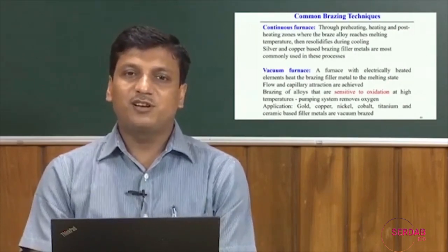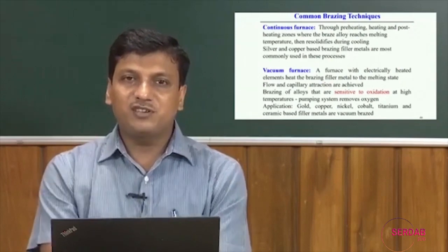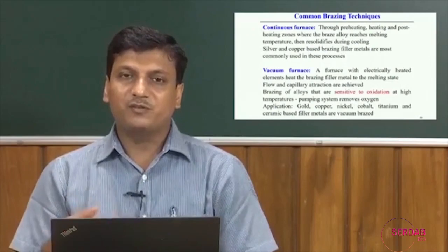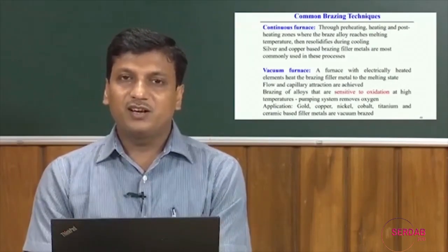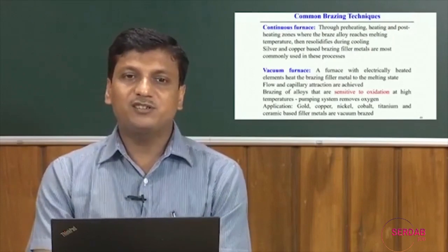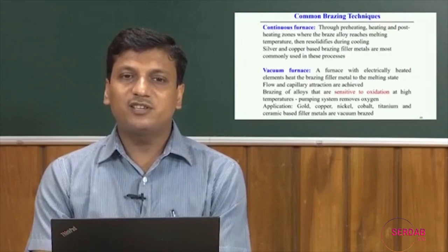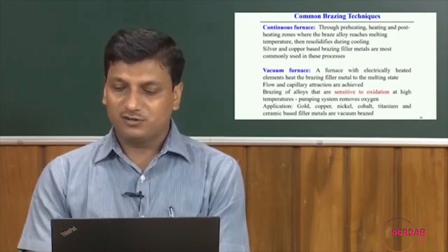The pumping system removes the oxygen from the zone where the workpiece is kept, and gold, copper, nickel, cobalt, titanium and ceramic based filler materials are vacuum brazed.